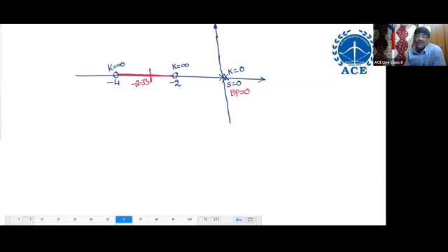So now draw the root locus diagram. What is the root locus diagram? As k increases, the poles leave the real axis here. It cannot move right, it cannot move left because there is no root locus branch. It leaves the real axis, just like a breakaway point. Then it turns toward the left and enters at the break point.